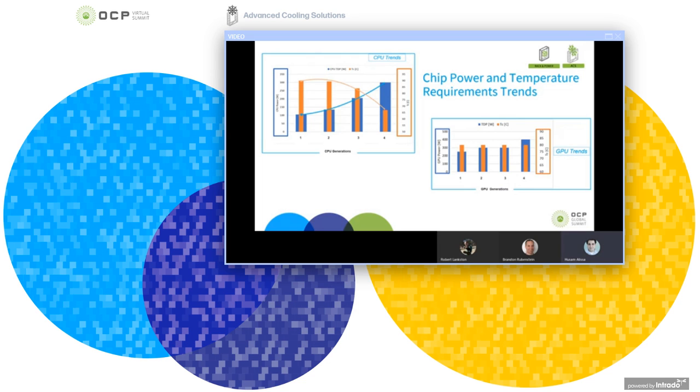Could be number of cores increasing, or other features are added to the chip. Similarly, looking at the GPU charts, power has been going up constantly. And sometimes it is possible to have the power increase accompanied with a reduction in the required T-case due to power increase or die size shrinking, etc., which makes the thermal solution more challenging.